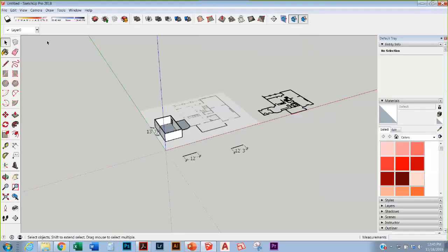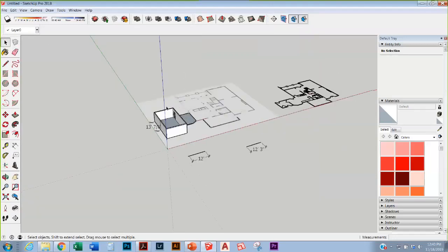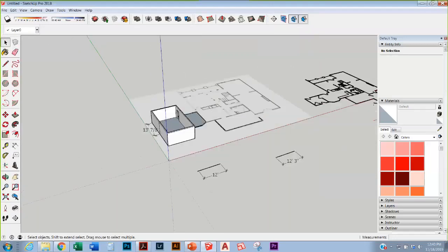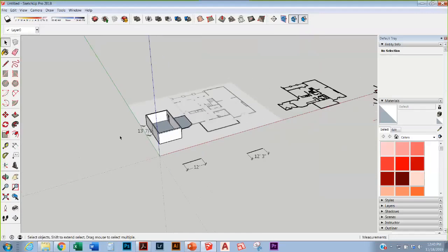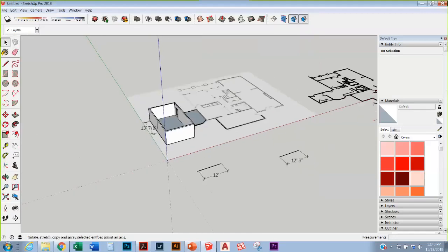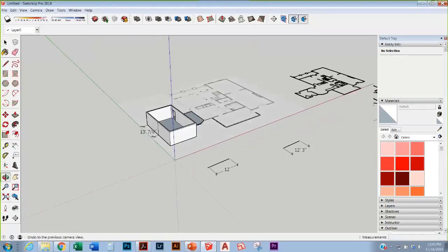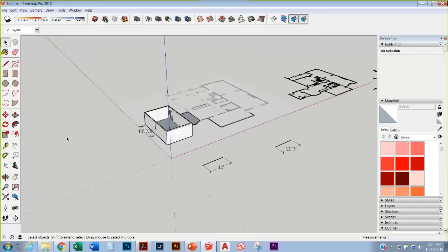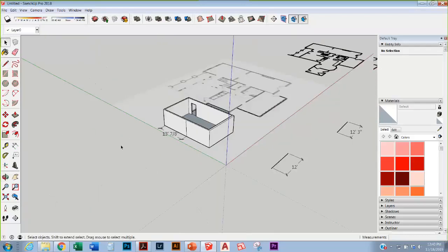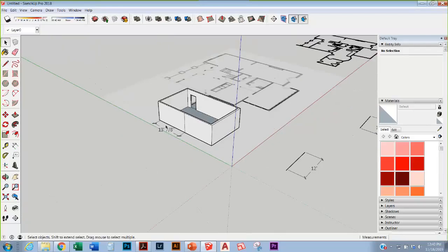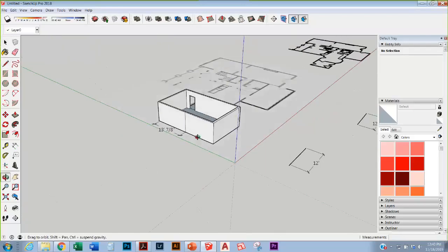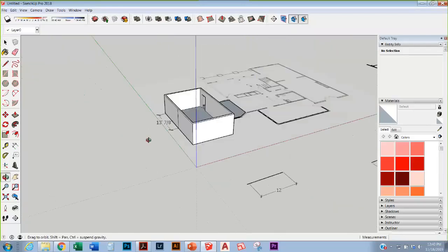All right, so some of our tools. The biggest thing is how to navigate around. The first thing is your rotation, right? So you can use this tool, which actually allows you to spin your model around. But again, using the tools becomes really cumbersome, and it's much easier just to use your mouse. So not your wheel, but your second button on your mouse. If you press that, you can move your mouse around, and immediately that goes to rotate.